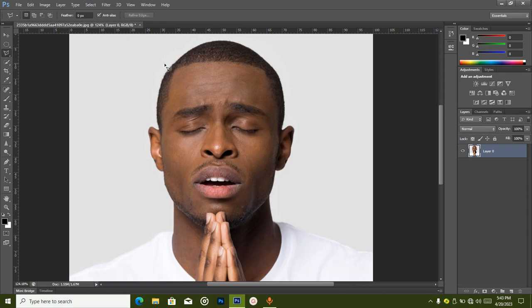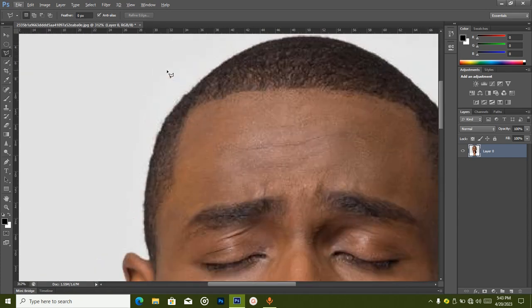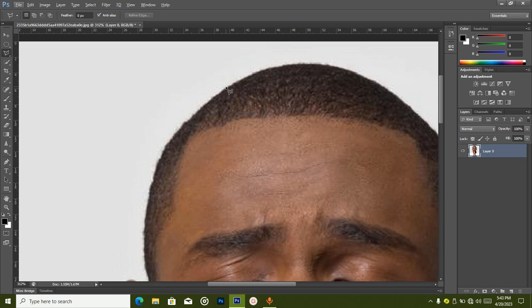So assuming I want to remove the background here with the polygonal lasso tool, I can click here. Now you see I don't have free will to select it freehand, but I have to move it to where I want to select and click again, then click gradually like that to make my selection. So if I bring it back to my origin where I started the selection, now I have made a selection here.